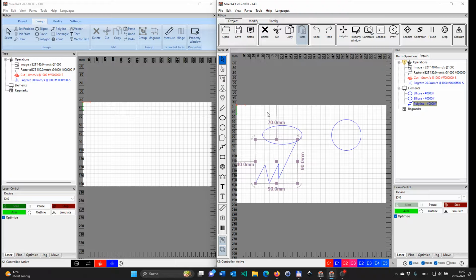There is one additional new tool, which is sometimes a useful thing. It's unfortunately not available for all the different things, but for certain things there is something available, which is called the parametric edit of a shape. For instance, if you click here on that circle and you click on parametric edit, you will see that now 2 points have been highlighted, and you can move them and change the thing quite conveniently. Keep a point on the circle fixed and just change the center point, and so on and so forth. This is true for a couple of other things. We'll come to that in a separate video.